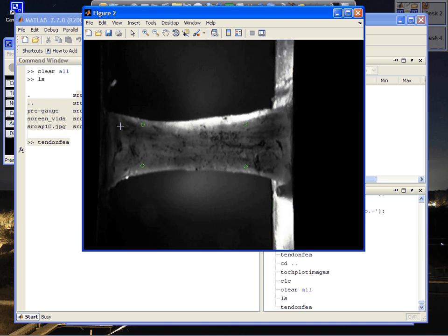Once again, starting from clockwise, you're going to, starting from the upper left, start your line segment and continue that line segment until you reach just the inside of the circle. Select another point. Then select the inside of the second circle. Select another point. Then proceed outwards from the point to the right. Select any point. You could select here or here, but I try to keep the two sides sort of symmetric. So I select this point, and then I'll move down here and select this point.